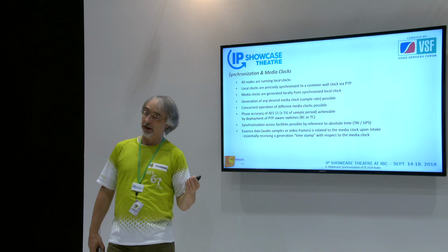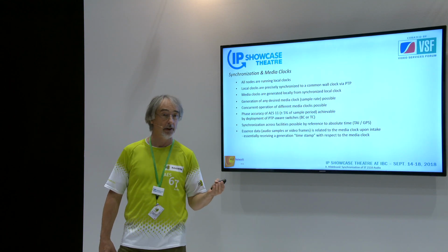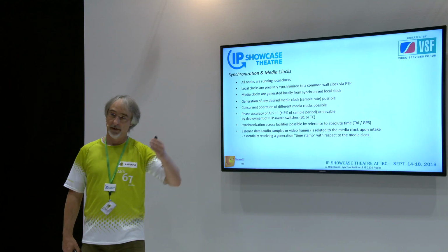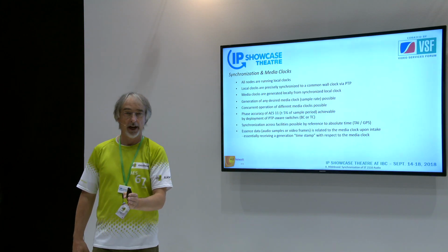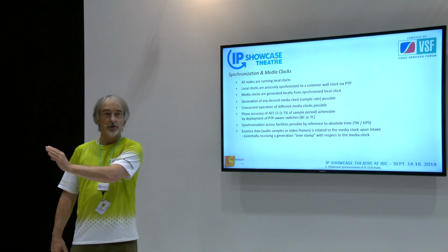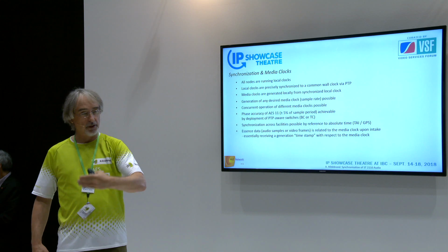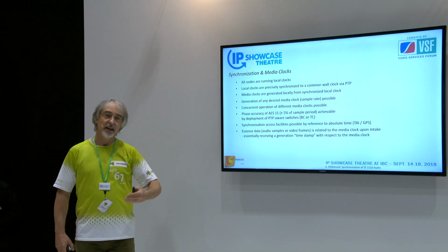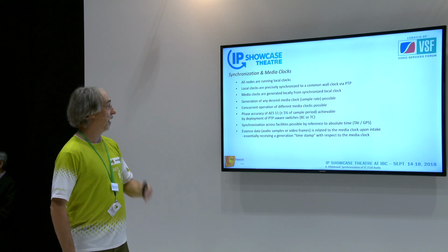Now, the devices all have time, right? They have precise time, down to the double-digit nanoseconds. So at the very moment a sample is being gathered from the input side of things, it receives an accurate timestamp. So once that sample travels onto the network, any instance down the line, receiving that particular stream, can know exactly when a particular sample has been generated.